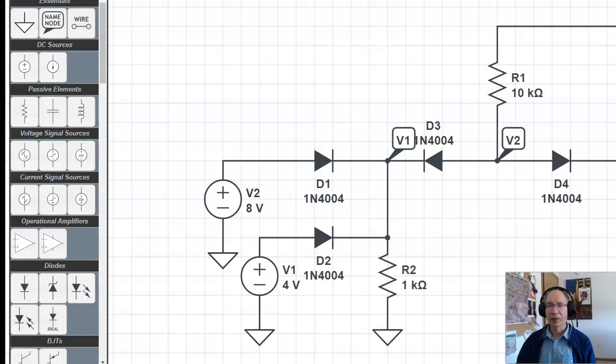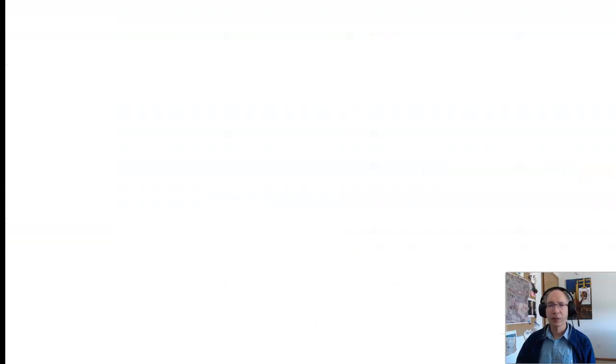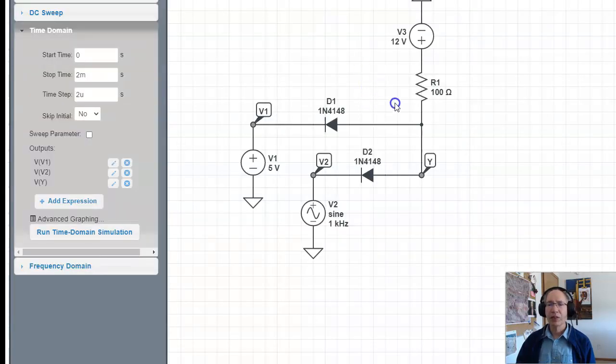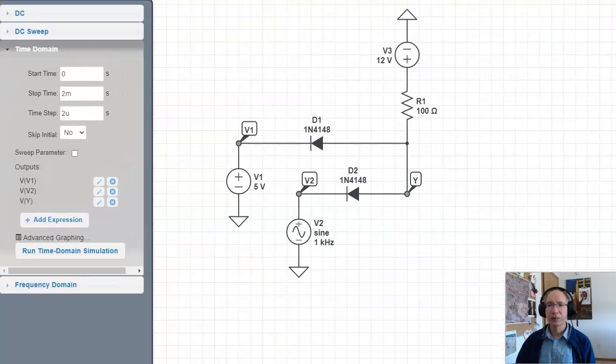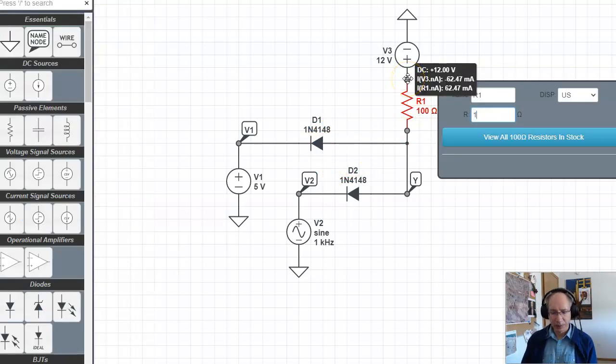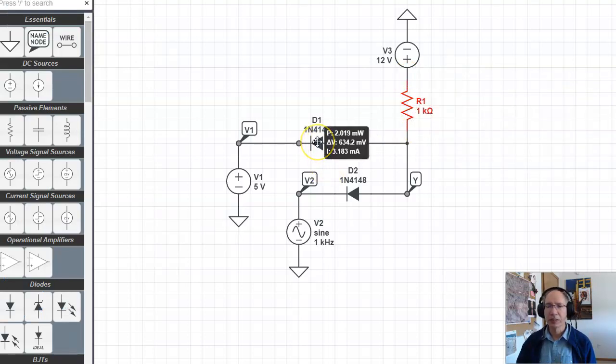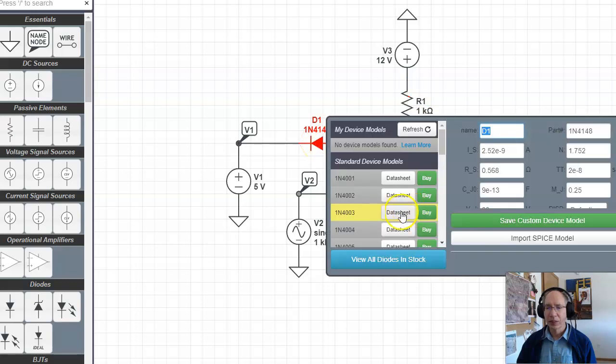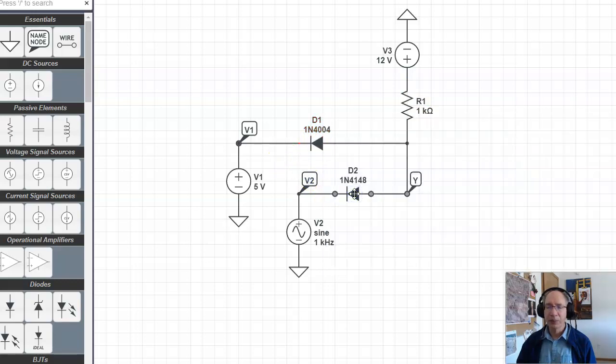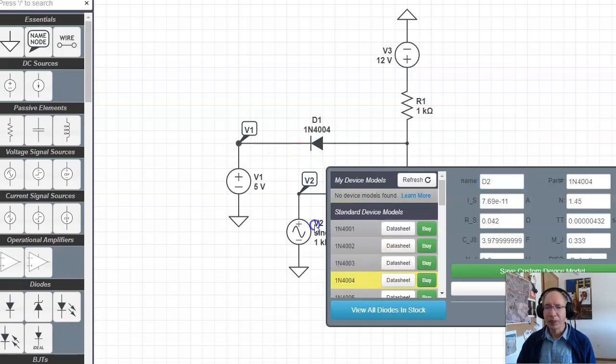Again, in CircuitLab, I can check that. Get the right circuit. If I flip the diodes, and I've got to change this guy and go to 12 volts rather than ground. Doesn't really matter what R1 is. Let's change this to the ones we have in lab, 1N4004 diodes. Really, all diodes behave about the same. Doesn't make a huge difference which diode you choose.